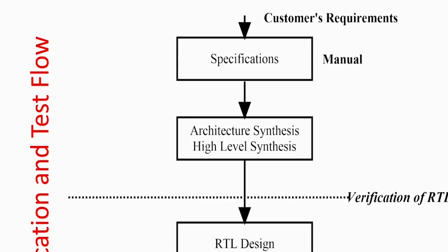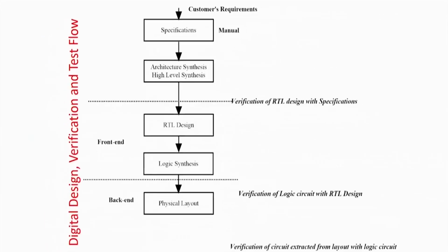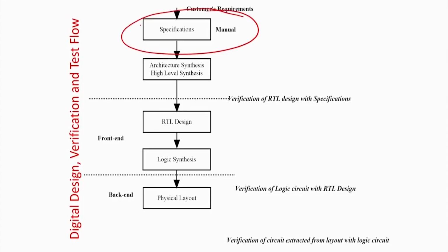Then as an engineer you have to model it using what can be synthesized as hardware, and decide how the block level implementation will be. Say somebody says I want to design a calculator, you have to tell whether it's a scientific calculator or business calculator, then what the adder will be, there will be a multiplier, a subtractor, what the keyboard will look like. All these specifications you have to design manually, and give high level block diagrams. Now you can say that this will be an adder. Everybody knows how an adder is to be implemented, and there are automatic tools which will do it for you. But exactly whether you require a serial adder, or a carry look ahead adder, or you want to implement a multiplier by using adders, nobody can automatically do that. That is called specification, and the high level design block diagram is a manual procedure.